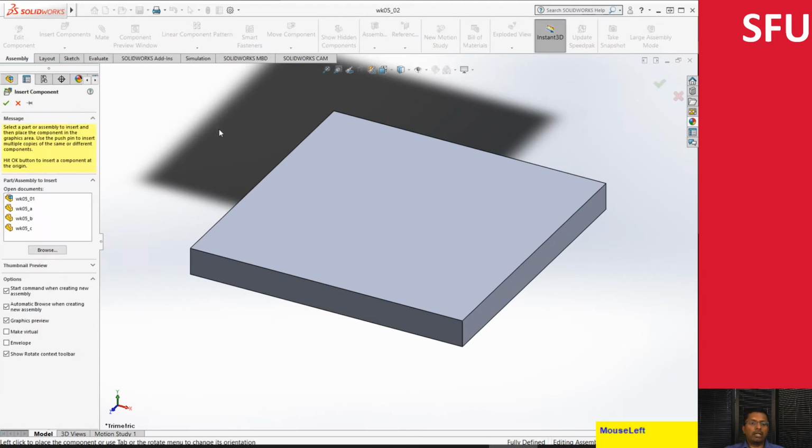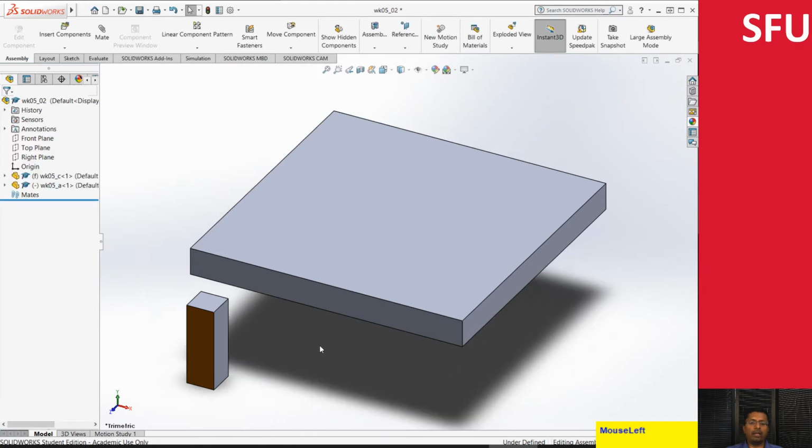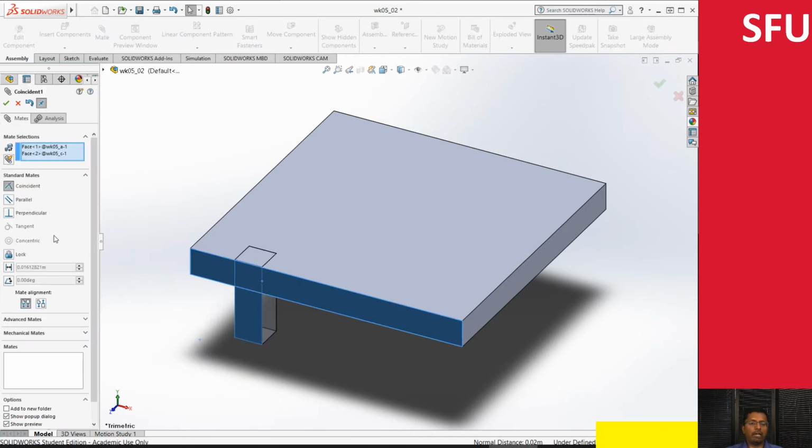So we're going to insert component here. Both of these are the same leg, so I'm going to pick leg A. I know it's a little bit of a short leg, but that's okay. Once again, I can click this guy and this guy. Since I moved my mouse, I lost the context menu. That's okay, I can click on this and click. It automatically makes it coincidental, and then we say okay.